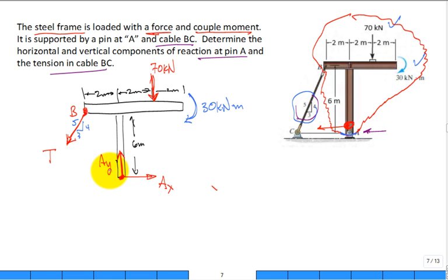I pause, I really look at this a long time. Do I have any information that I need to put in the free body diagram, or is everything there? Did I miss anything? Look okay? Some of you had it perfectly. That's good. Go ahead and include orientation, angles, lengths, dimensions, things like that. That's important, as well as distinguishing your forces.